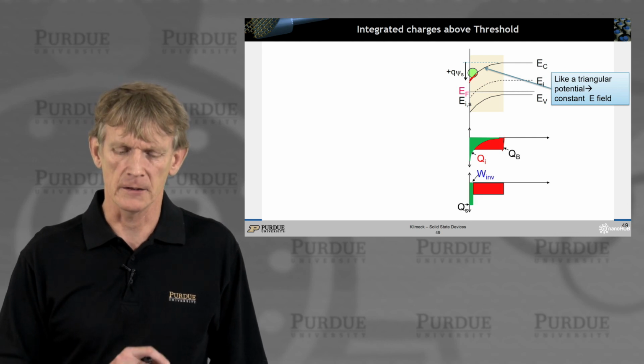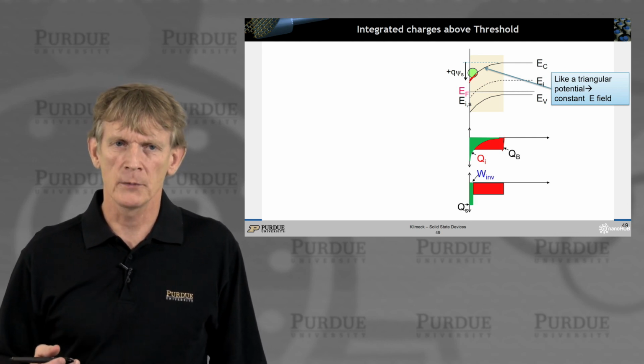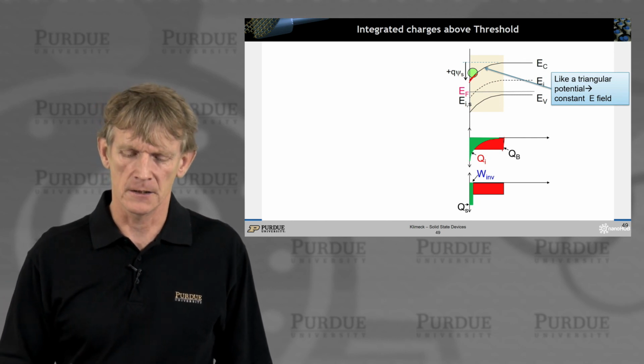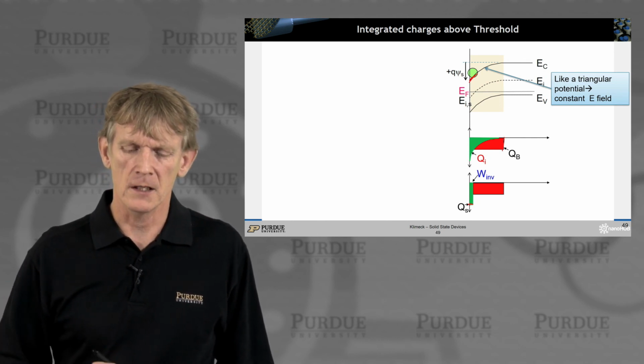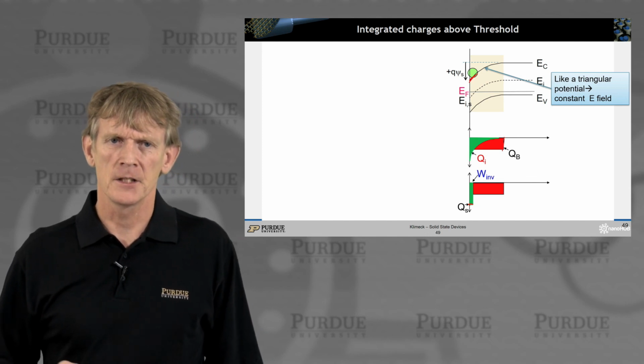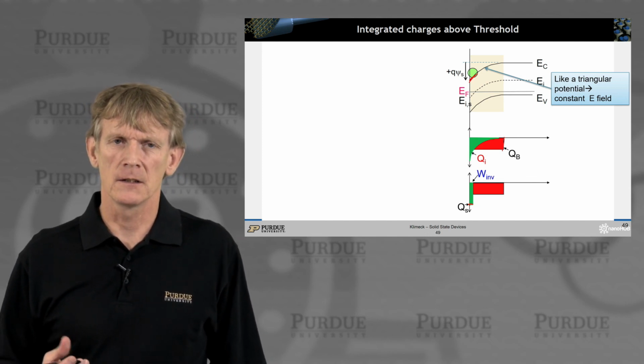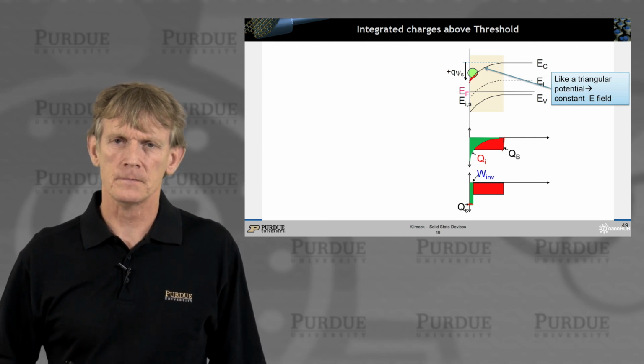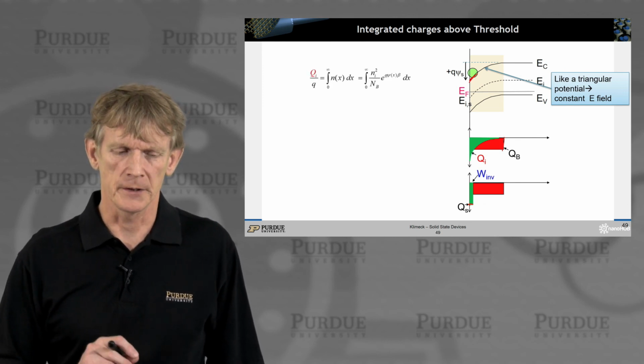That's plotted in green. We're going to approximate this, since it's really an exponential, by almost like a sheet charge, right? We'll call this green a sheet charge that is in a very small dimension of a few angstroms. That's how narrowly confined the charge will be.